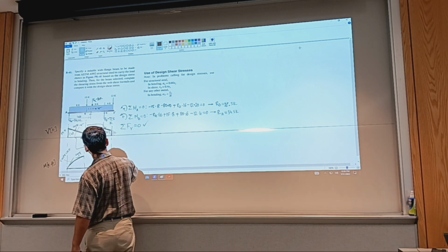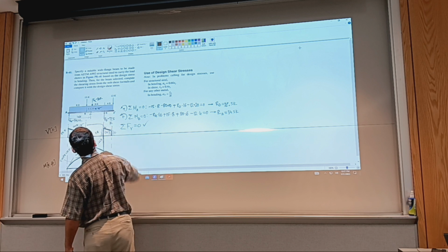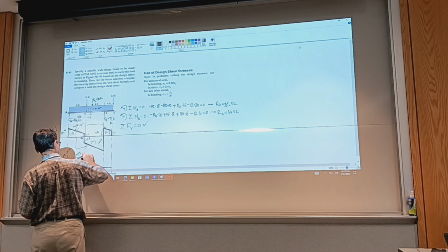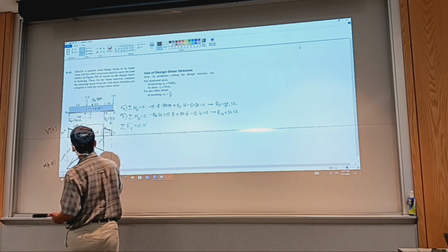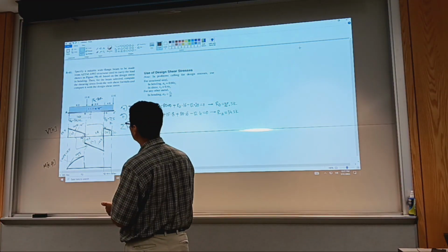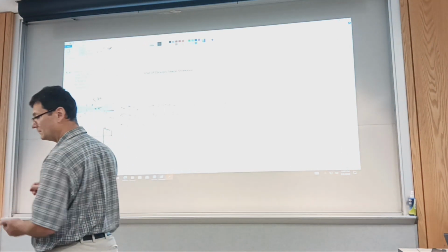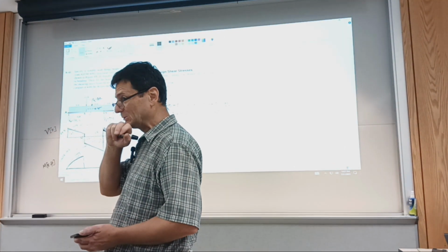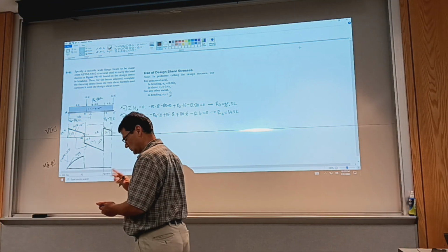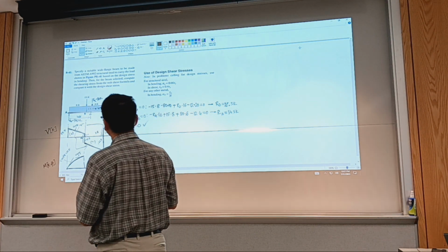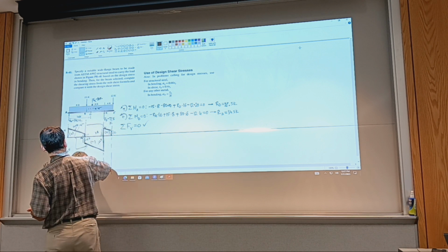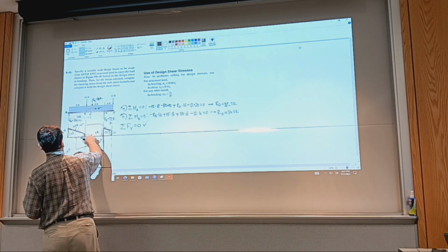So let's see what the net bending moment is at D. I have to calculate this amount of moment. That's going to be the area of a trapezoid between A and B under the V diagram. I wish more students were in class, because in the second test, really there was no fully correct bending moment diagram. The shears were fine on some of the students, but the bending moment diagram was not fully correct on anybody's paper. Okay, so what's the area of the trapezoid? That will give us the moment here. So it's going to be 34.5 plus 2.5.